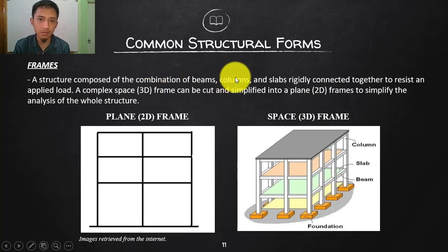Okay, what is the difference between beams and columns? Beams are actually mainly loaded laterally. So this is an example of beam. The main load of a beam is lateral. The column, that could be loaded laterally, but the main load here is axial. The difference of column and beam is that in beams there might be an axial load, but that is negligible compared to the lateral loads.